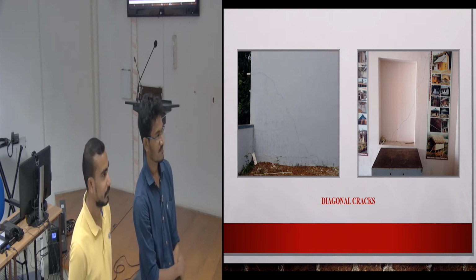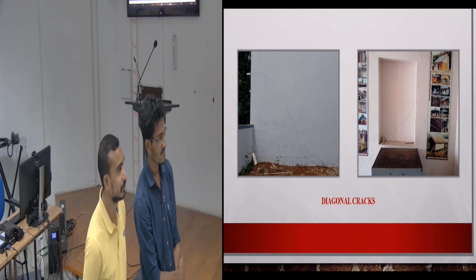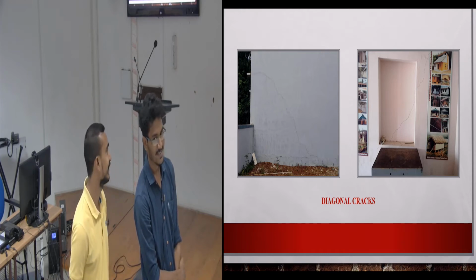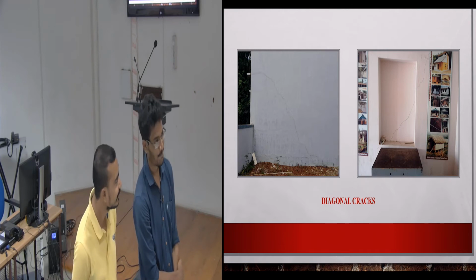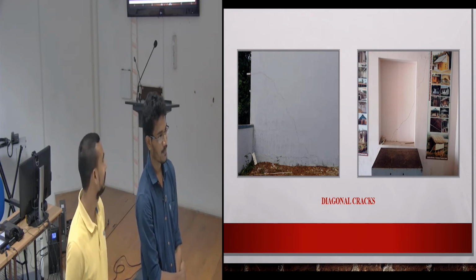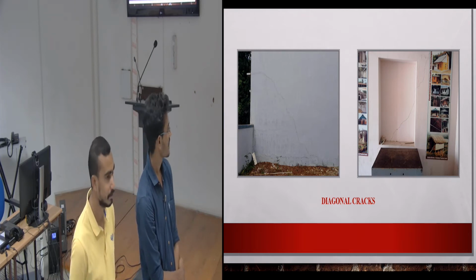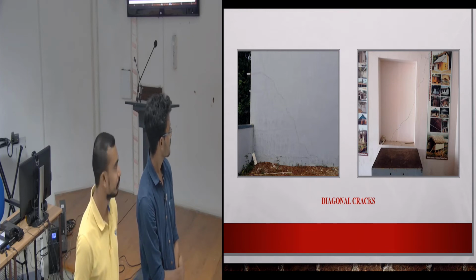So if you have got a similar crack on the other side, then it is a structural crack. That has to be done. This will widen as the years progress. Due to the stress concentration, it will widen. It's a construction fault.